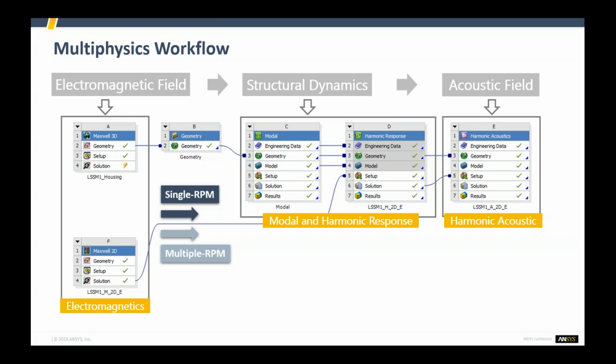3K hertz. Okay, that sounds okay with me. But my experience is that I've run a couple of Simplorer projects, and what I noticed is that this time step is somewhat crucial to your simulation. And not only the H mean, but the H max is also important.